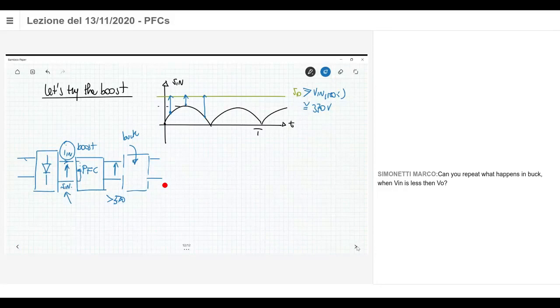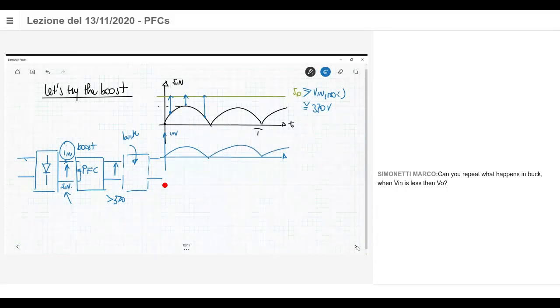They exist, they are sold in the market. They typically, all electronic equipment have a PFC, say, following the rectifier, okay, in order to withstand the normatives and, say, the regulatory mandatory rules for your equipment. So there is a control action, which is a huge effort to, say, make this current flow. So if you look at the current I in, it should be convinced to follow this path. Okay, in that case, you can have exactly the behavior you want. The power factor is 1.